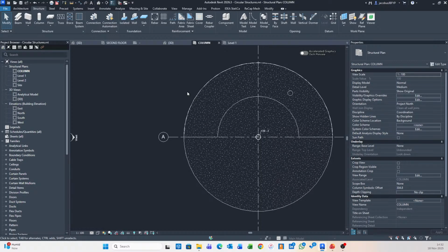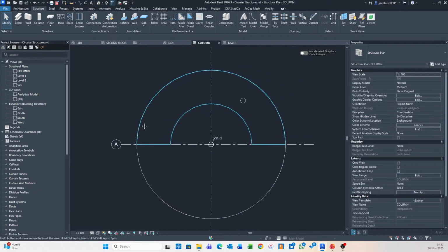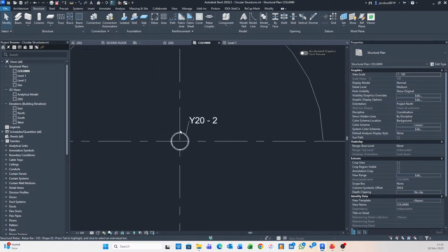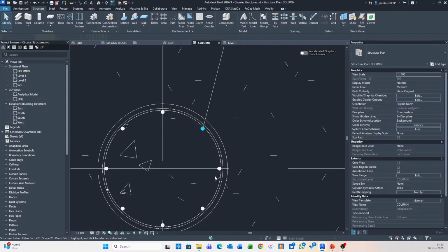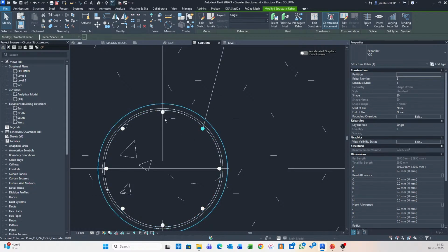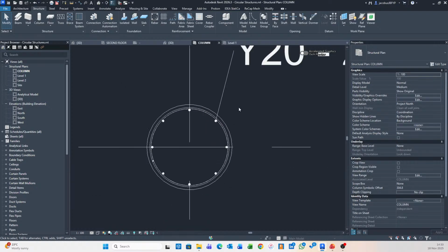So hopefully Revit will, or Autodesk will, with a future update, improve this process and even potentially allow you to add bars to a set, and not make it difficult for you to do that. You do have things like Graytex Power Pack, which can have rebar functionality, which allows you to add different bars to a set, but that in itself has its limitations. Right, so please do keep that in mind.